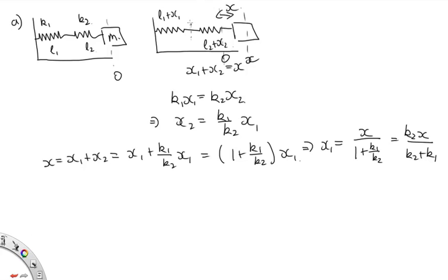Now let's just consider force 1. So we have some total force here. Total force is going to be pushing this back here and will be equal to minus Kx. But the force on spring 1, F1, will equal minus K1 times the extension of this first spring, x1.